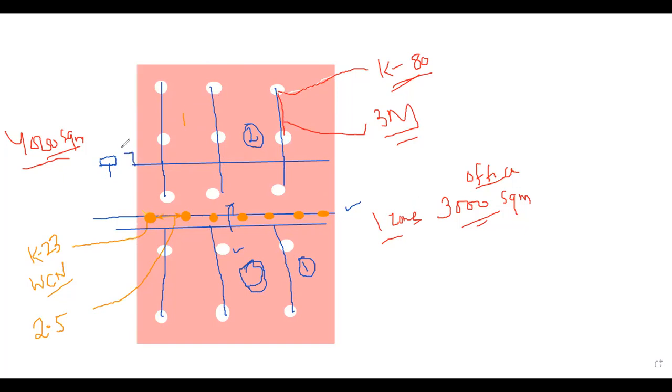So here you have a flow switch, and for this line also you'll have a flow switch. In this pipe we'll have two flow switches. First understand one zone, then we can understand the different zones. One flow switch will be connected to your fire alarm panel.